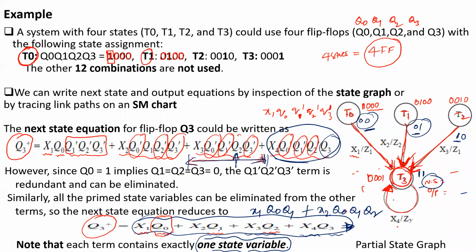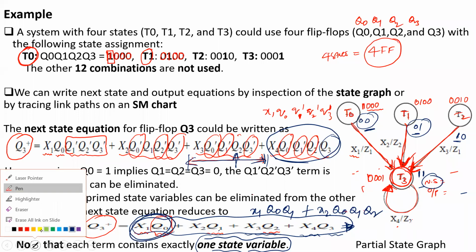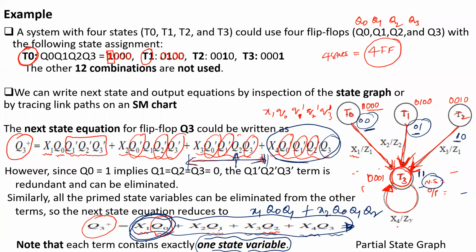Okay, but using this one state assignment technique, one particular term is completely responsible for finding out one particular state variable only. That means this is responsible to find out only one particular state variable. Each and every term is responsible to find by using one state variable only. That's what we have to identify. So to implement this equation, less hardware is required. That's how, if you're using the state assignment technique, there is a possibility of less hardware when compared to the state encoding technique.